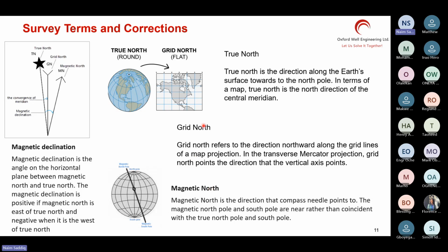If we were to do the course, Innova has software that calculates the correction, and you can visualize it, or hand calculate it, because this is what separates you from brand new people. If you know whether the corrections are right or wrong, because the impact is very bad: if you get it wrong, your actual well will be very far from where it is supposed to be.